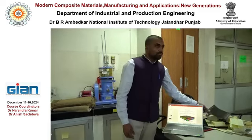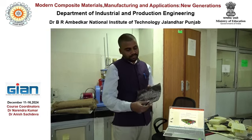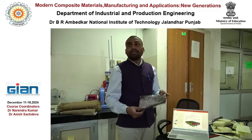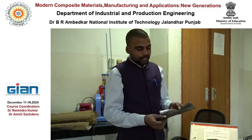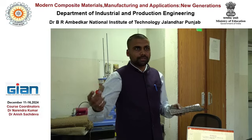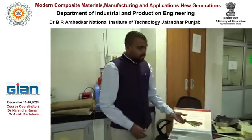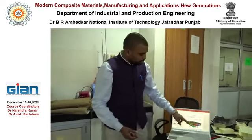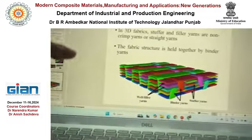We know that if you want to produce a laminated composite out of this simple single layer, normal 2D fabric, and you want, let's say, 1 centimeter thickness, then based on the thickness of your single layer, you have to take a number of layers. In case of 3D fabric, here also if you want 1 centimeter thickness, you can take number of layers and you can produce the 3D fabrics.